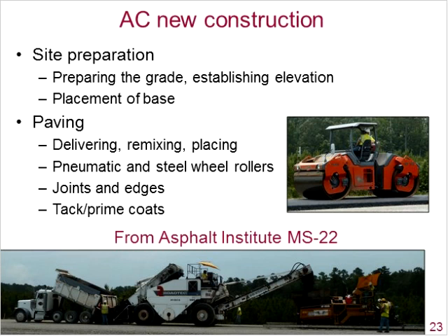And when you do go to the paving, you first need to deliver it. Often asphalt concrete is remixed now. In that picture on the bottom, the machinery in the middle, the RoadTech machine, that's a material transfer device, and what happens is the material goes from the truck into that material transfer device and it mixes. And that mixing eliminates a lot of the segregation, both rocks and temperature, so you have a very homogeneous mixture going into the paver, which then lays it down.